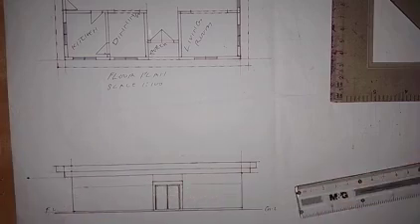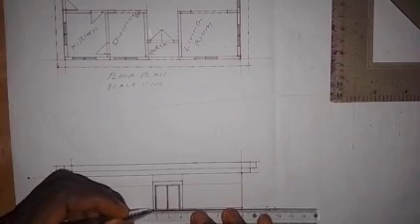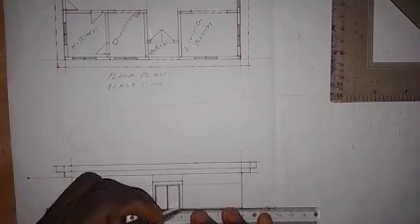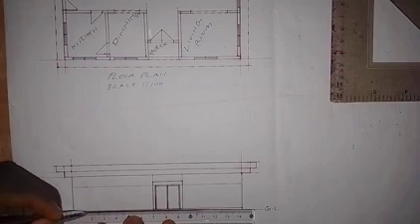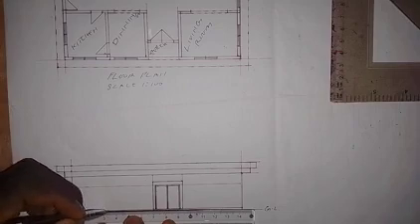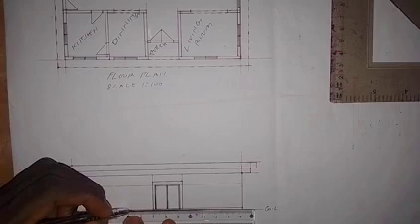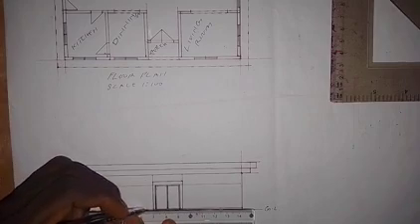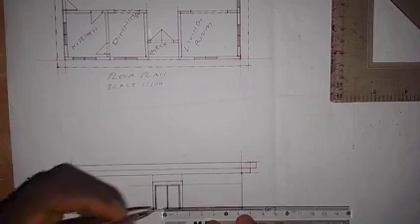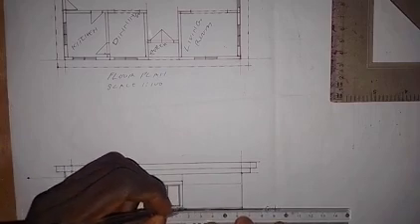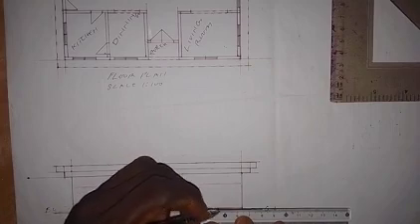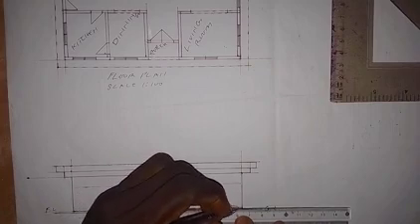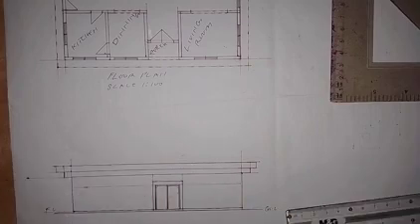Here I need to make this floor level, which we are going to see. For this part, it's going to be drawn with short dashes line for the inner part of the building. We can't see it from outside, so that's why we need to draw this with short dashes line. That is for the floor level inside the building, so you cannot see it from outside. So that's what I've done.